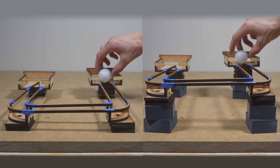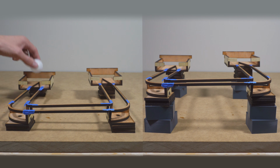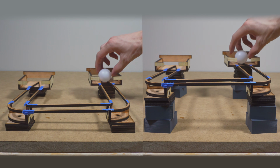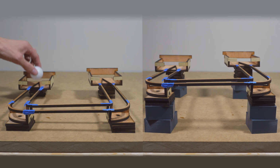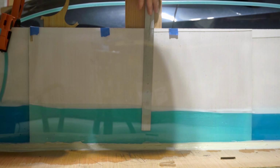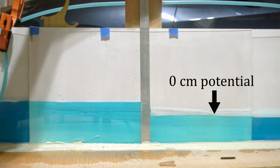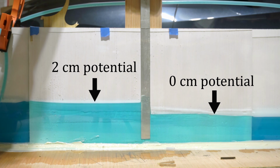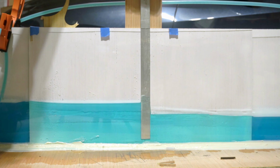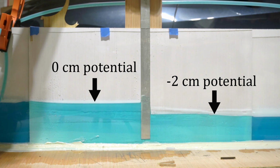If you somehow charged this entire wire and the absolute voltage was way up here, it just doesn't matter because the electrons can't leave the wire. All they care about is the height of the hill they can see. In the water model, if you want to use height as a voltage equivalent, you need to choose a reference location. If I choose this as a reference point, we could say this whole area is at 0 height, and this area is at 2 centimeters height. Or we could drop our reference on the other side, and this area is at 0 height, and this area is at -2 centimeters height. The absolute position really doesn't matter.